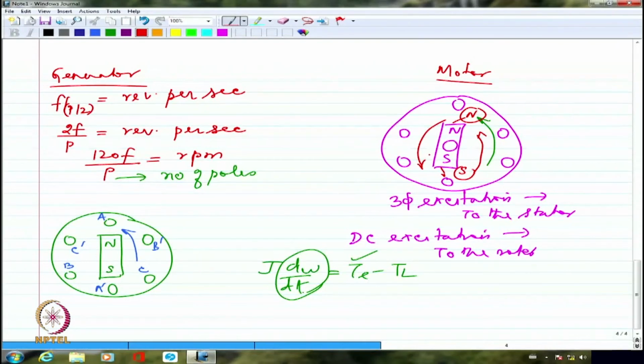The rotor is wanting to catch up with the magnets, but it cannot catch up with the magnet which is created by the revolving magnetic field because the rotor has a finite inertia. So the rotor is not going to be able to get up to speed right away, because of which it will face repulsion sometimes, attraction sometimes. So there will be only a dwindling motion.